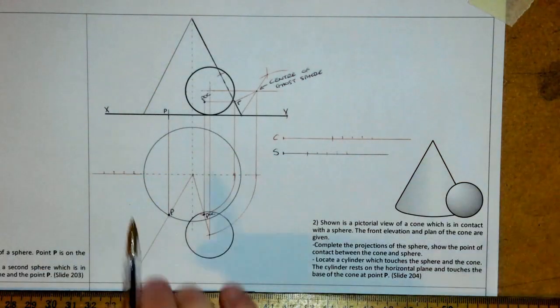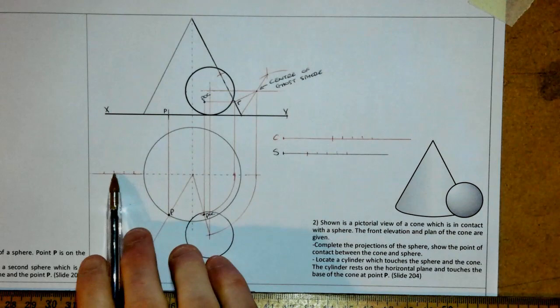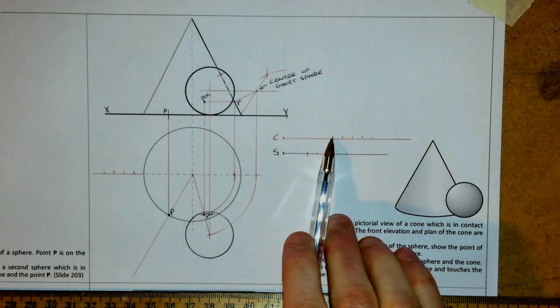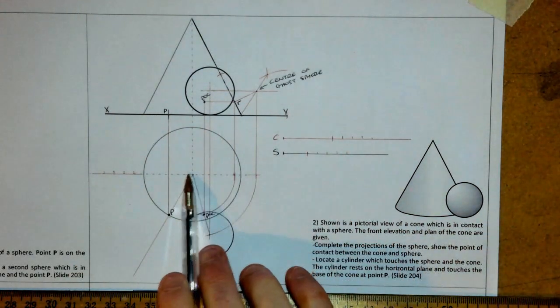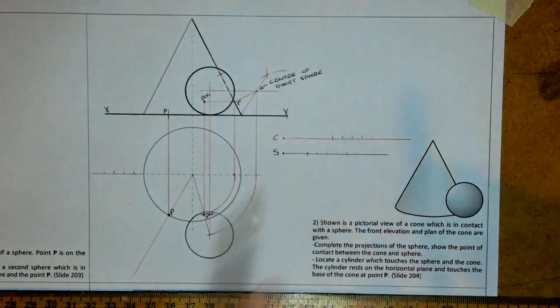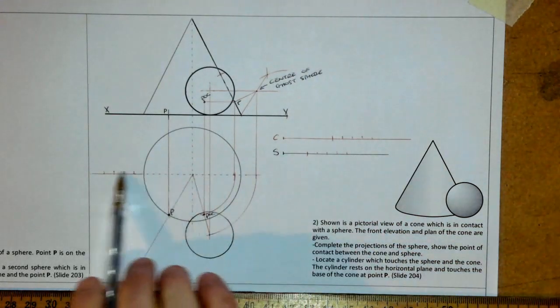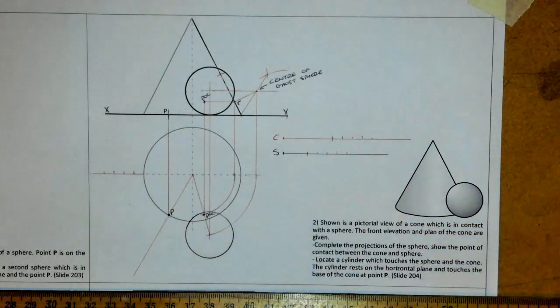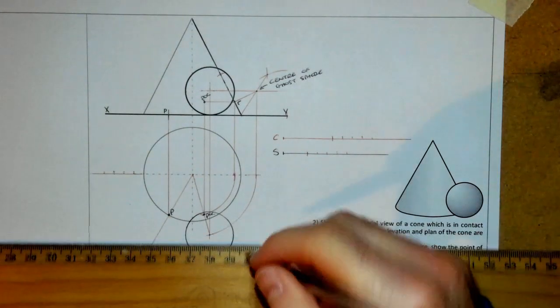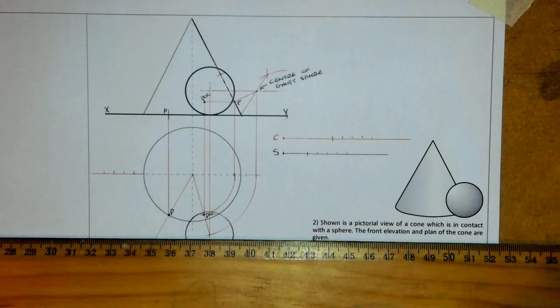Essentially those 5s that I've done, 5, 10, 15, 20, are the same distances as these ones here, because that distance there, the radius of the cone, I've marked it out here. I just think it's easier to keep it on the actual drawing rather than going off doing it somewhere separately, but whichever works best for you. Now you could also do it down here as well, so I'll do it from the side of it here.